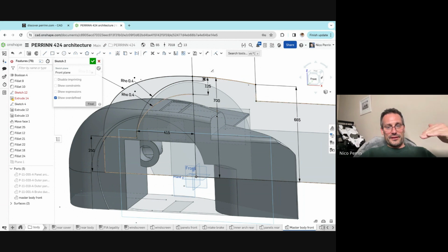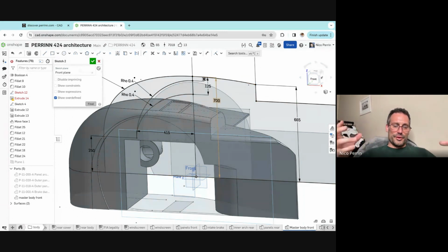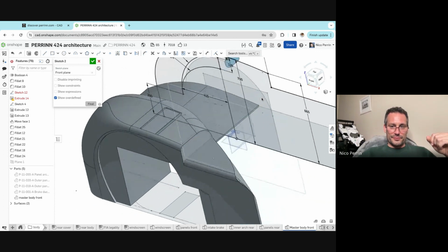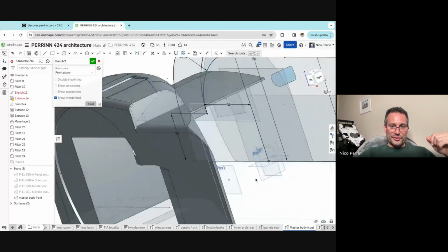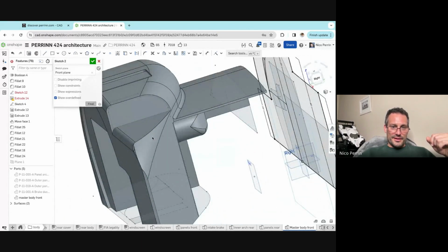But yes, typically if I close this exit, I'll go to aerodynamic test in CFD. I would expect the pressure under the wheel arch to increase a little bit, which will actually reduce the front downforce, but the drag will reduce as well because we have less dirty air coming out. So typically a test like this would be done. I can see there's an issue here as well with this detail.